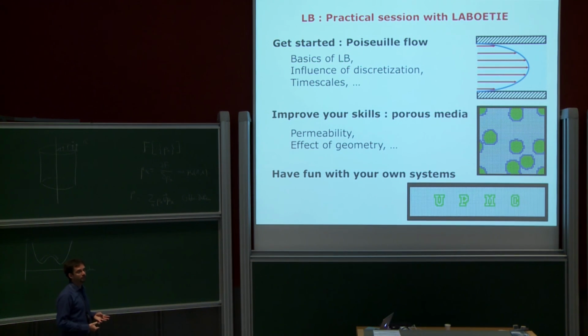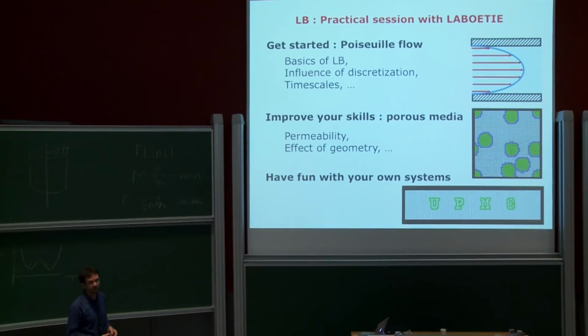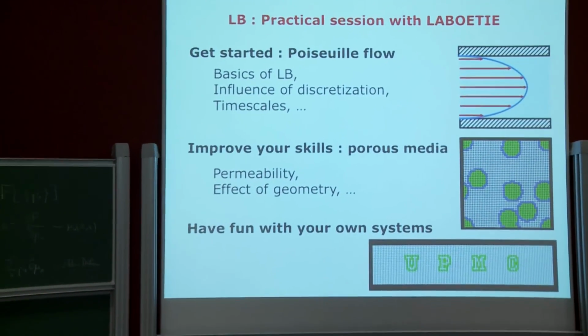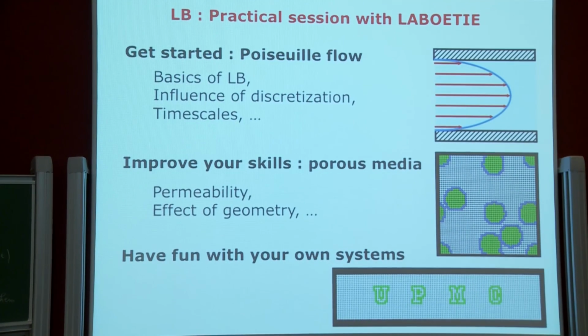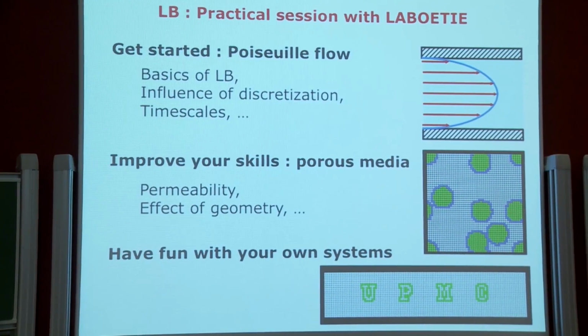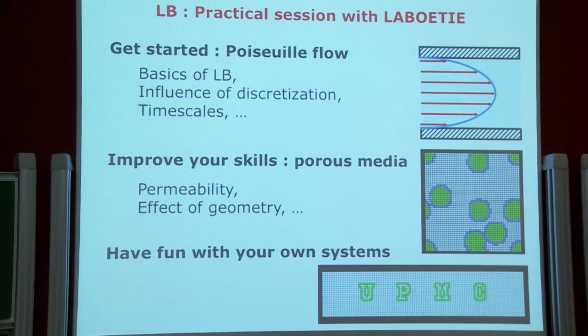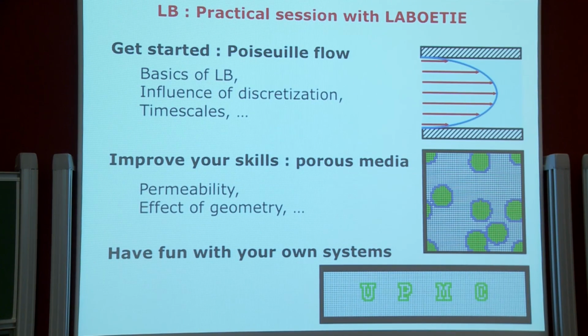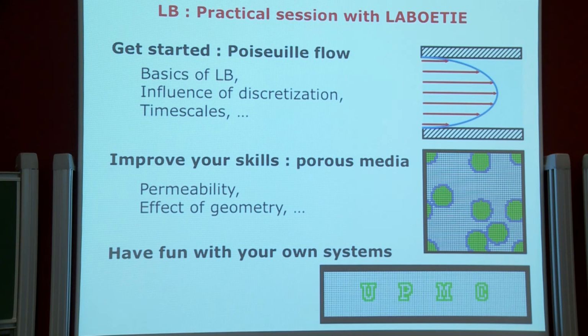And obviously, you want to start with simple fluids in simple geometries, because that will give you a flavor of what is important, how to choose the simulation parameters, and whether the assumptions that we've made to derive the Lattice-Boltzmann algorithm are justified in the conditions you're going to simulate. And so we'll start with a Poiseuille flow that I've already mentioned.